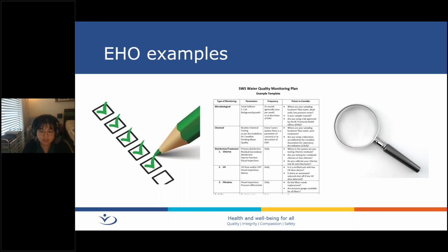So in this case, the water supplier can perform a check of the system, again, from source to tap, and review their maintenance log to see if the issue can be identified, whether it is a treatment failure or they didn't notice there's maybe a pressure differential that may indicate there's a break in the line causing consistent total coliform counts.